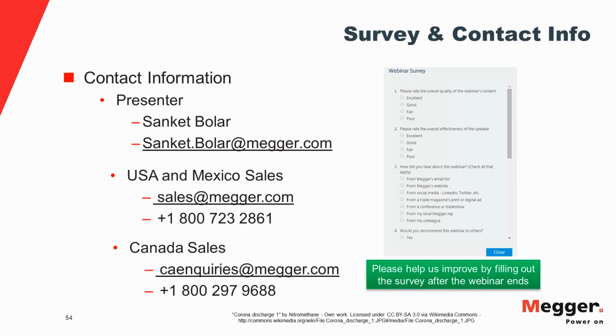The 8% limit is given for voltage THD. So it's for voltage THD, not current. It's just referring to the voltage total harmonic distortion. As far as I know, I don't think there is any limit for THD or TDD on the current. I could be wrong. Maybe Andy could help out with this. But the 8% limit that I mentioned in the European standard, EN 50160, is for voltage THD.